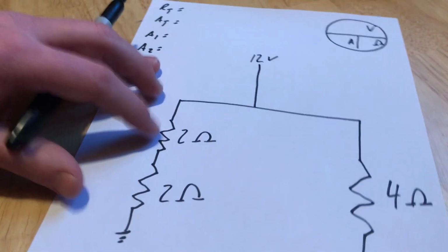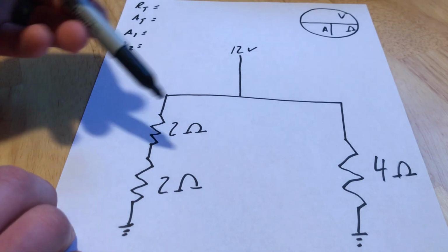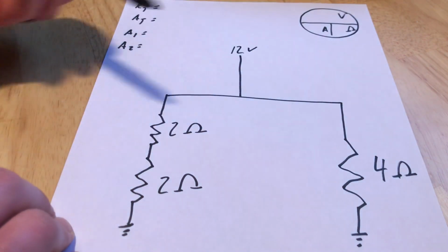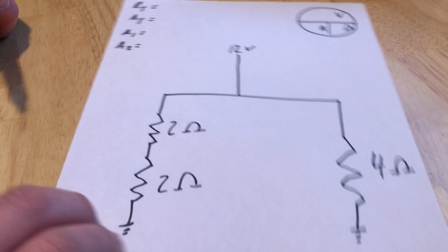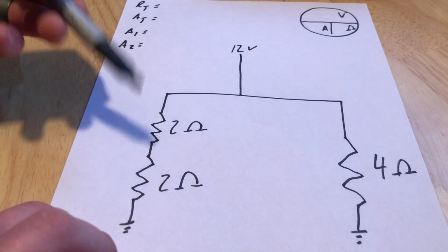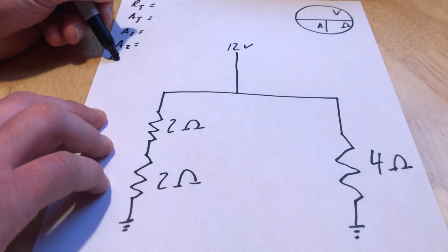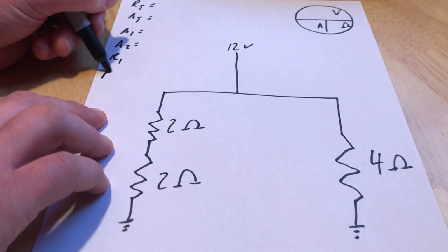All right. Getting close to the end, but not quite there yet. Now all of a sudden we've got a parallel circuit with 2 resistances on one leg, one on the other. So we need to figure out total circuit resistance. But I don't even know the resistance of this leg. So let's add a couple things here to our list. R1 and R2.